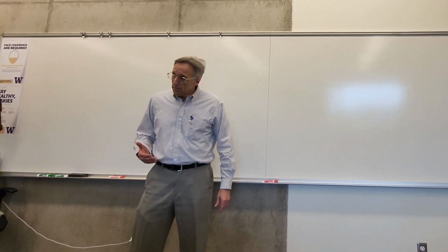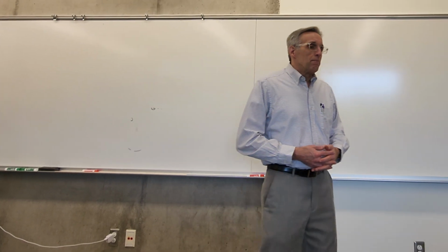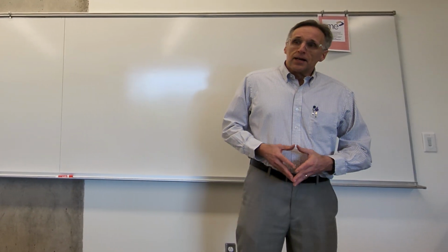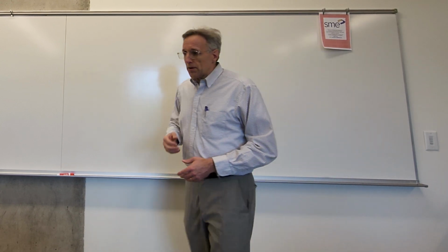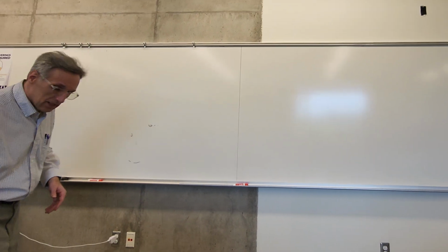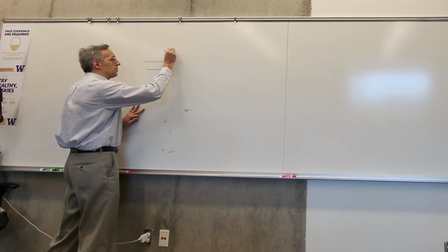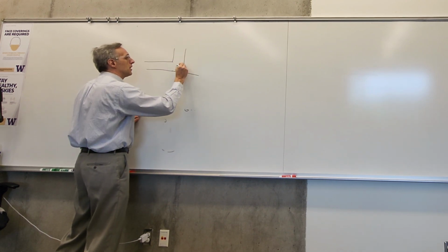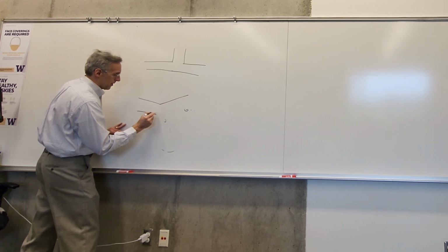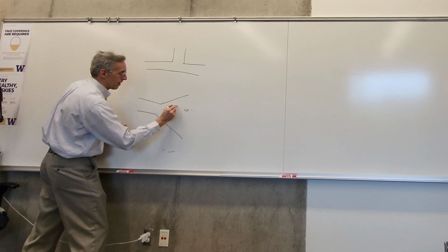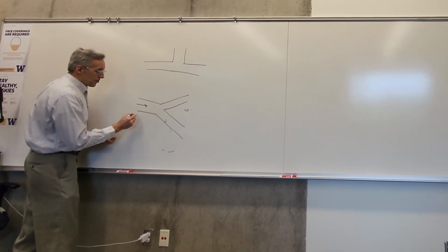In the fan distribution example, I tried to include both the equivalent length method and the loss coefficient method. In that example, you can see that for fittings like a T, or we can have fittings like this, and these are diverging.